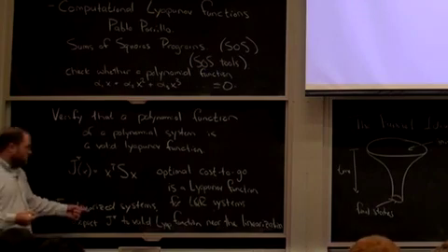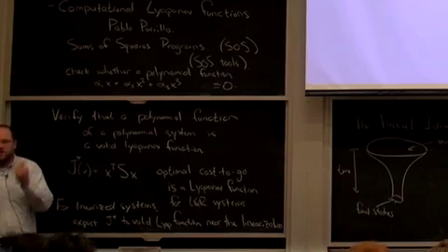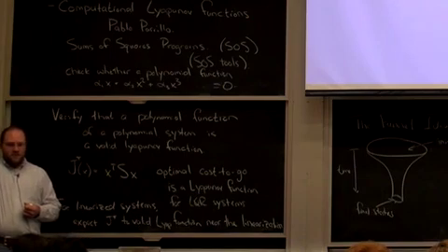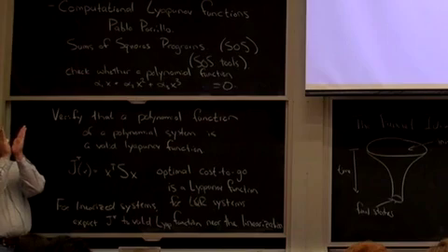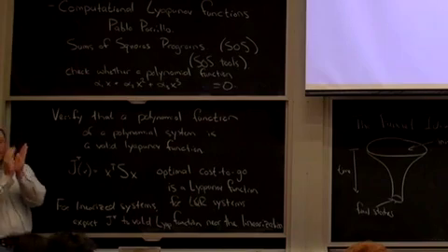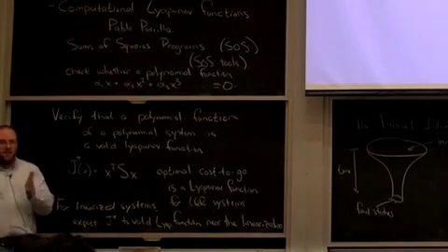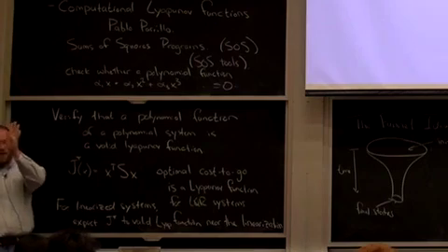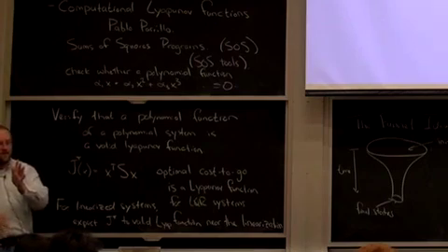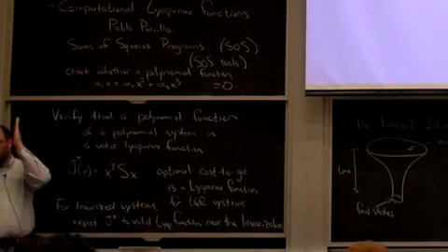You remember when we're taking a linearization and doing LQR, we already know that the basin of attraction is going to be something finite. We talked about that with the acrobot, right? I do a linearization around the top. I know if I'm near that point, it's got some small finite basin of attraction. If I'm inside that region, it'll go to the goal. If I'm outside that, then the linear controller design isn't valid for the nonlinear system. Eventually, you're going to get far enough away that it's not going to work. I think I even showed a simulation of it doing something crazy, right? So what we did was we designed a controller that got up there, and then we turned on the linear controller. All was good, right?